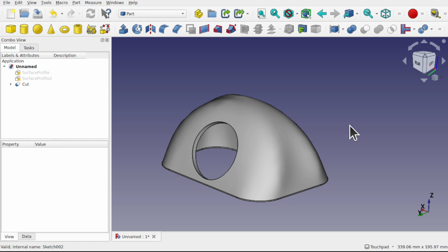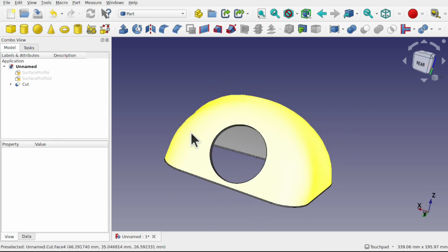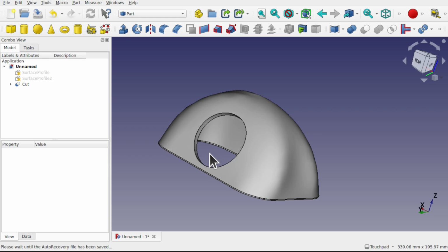In this video, we're going to be using those line attachments in a surfacing workflow, attaching to something like a base sketch by clicking on a number of vertices and selecting a sketch, and learning how to attach that with those certain attach modes to allow us to control the curvature of something like this object. So I hope you're finding all these tutorials useful, and let's have a look at this technique.